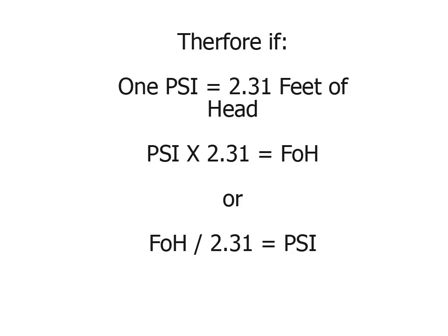Well, if the bottom of a water tower is 23.1 feet in the air, I divide 23.1 feet by 2.31, and that tells me I have 10 psi minimum of usable water pressure just from the weight of the water alone. If I have a pond pump making 10 psi at the nozzle, for example, then the water could effectively spray as high as 23.1 feet. Again, 10 psi times 2.31.